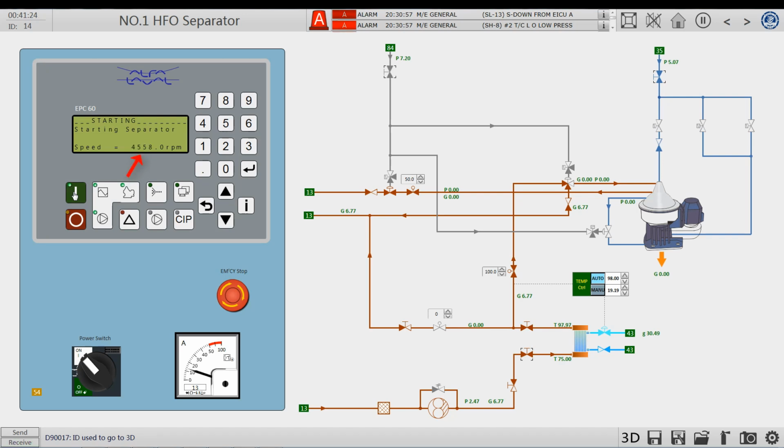After the fuel temperature and the rotation speed of the separation cylinder reach the set values, the LCD will show new tips, indicating that the oil separator is ready. It can be put into the normal separation operation. Start the oil separation program.